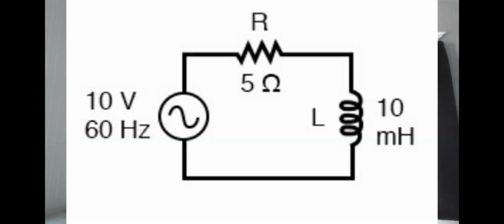In particular, we start by noticing that because it is a series circuit, we can assume the resistance in total is a simple summation of the individual resistances. Although this is true, we must also remember that while the resistor gives a simple resistance, the inductor does not. So it will be an addition of phasors rather than an addition of normal numbers, aka scalars.